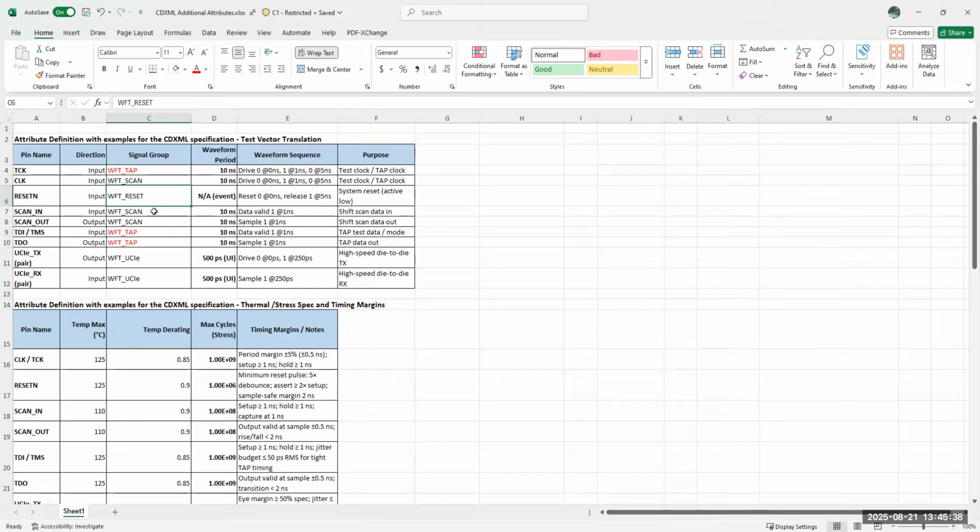Yeah, that's again based on the pin availability and how the designers come up with it. Ideally, reset need not be so complicated, but it can be a single one shared for the functional mode and test mode. But I have seen designs that have multiple resets going independently.